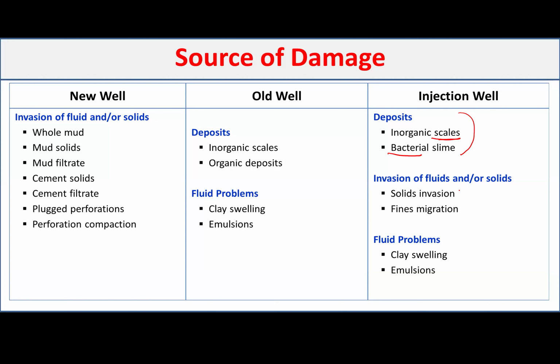Also, is the water that you're injecting solid free, or does it have some fines that can actually plug your formation? That's your filtrate, some solids that can go and precipitate inside the pores and reduce the permeability. And the last one is how compatible it is with the downhole clays. Clay is very sensitive to water.